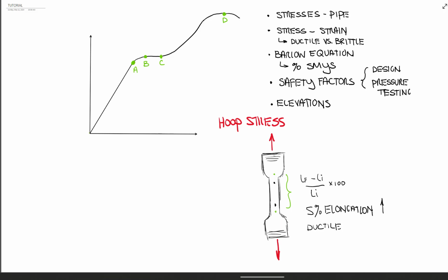And like I said before, as engineers, you want to use a ductile material, so it gives you a little bit of notice before it fails. Now, while they pull on this thing, right before it fails, it kind of necks down, which is actually the technical name. So this will thin out before it breaks, which is kind of intuitive. But anyways, necking down is another concept we should keep in mind here.